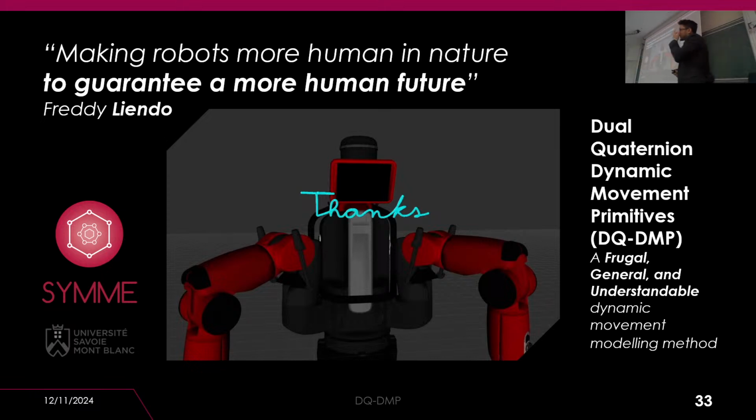What needs to be changed, adapted in order to make it robot agnostic? So you have to have a robot that has a similar workspace. Okay, let's say the throwing task, and that particular case study is the same. What else needs to be retrained? Yeah, so basically it would be the initial and the goal positions, the initial and the goal poses, effectively. Then the execution would be needed for both.